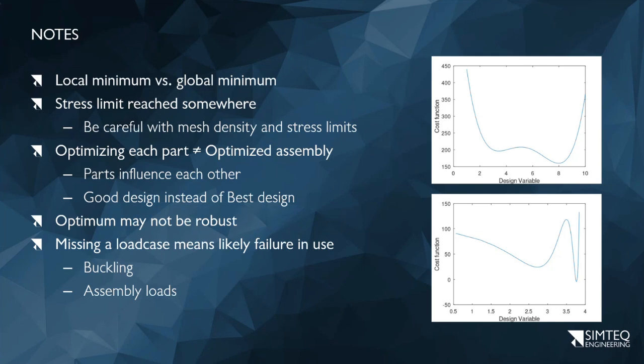One of the loads that can actually break that rim is the load that you need to get the tire onto that rim. So that's some kind of levering action. That's not part of the normal loads that it sees, but if it can't survive that load, there's no point in trying to manufacture it because it will fail. So this is something that you have to be really careful of.